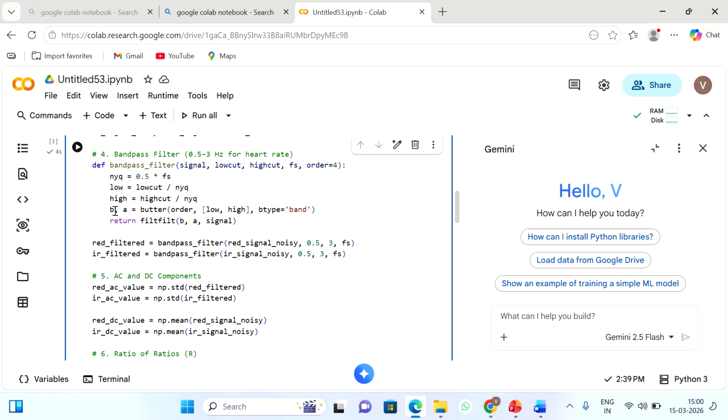Normally, we have to follow the Nyquist criteria while sampling. If the sampling frequency is greater than or equal to 2 times the maximum frequency content present in the signal, the criteria is satisfied. Suppose the sampling frequency is less than 2 FM, then aliasing will be the effect. Now what is aliasing? Aliasing means low frequency content will look similar to high frequency content.